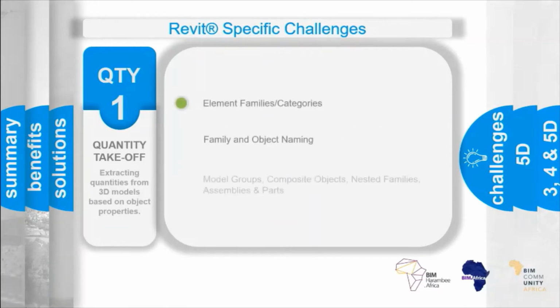At more specific Revit items, again, talking about families and categories, we said that Revit makes use of families in which the various model objects are contained or created. But it's important for modelers to note that every element or object in a model must be created in the correct family or category within Revit. So by way of example, ceilings should be modeled using the ceilings family and not in a family such as floors. Further examples being kitchen countertops, which should be modeled in casework family and not in a floors family.